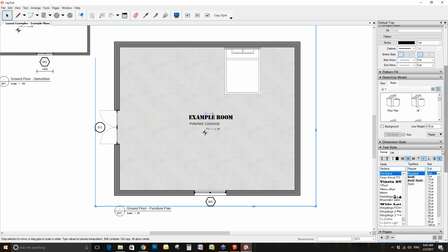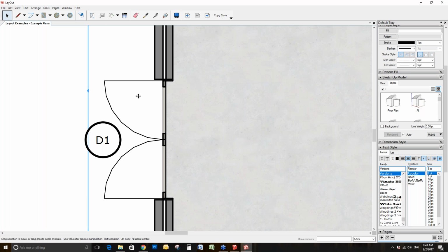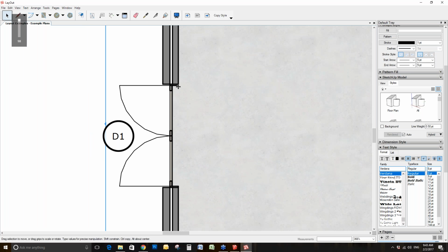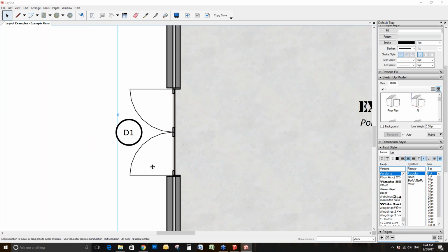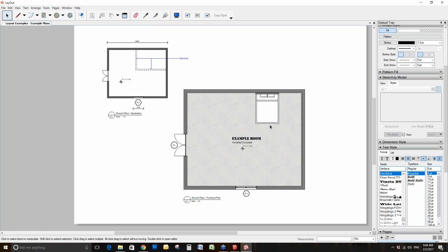So if you want to create very nice looking lines, but show color and texture too, you're going to be using hybrid. And hybrid is the best one to use with your Plusspec model. It's the one that I recommend. And that gives you the best of both worlds. It gives you the color and texture as well as the line and the line quality. However, if you're doing traditional 2D black and white, you might actually want to set it to vector.